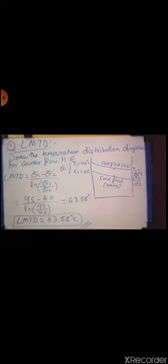The second part is to find out the length of the tube required, that is capital L. So as usual we have to find out the heat transfer Q. Q is equal to, you know the formula, m dot h into Cph into T1 minus T2, that is mass of hot fluid into specific heat of hot fluid into temperature difference of hot fluid. But here m dot h is not given, so we have to first find out the value for m dot h,